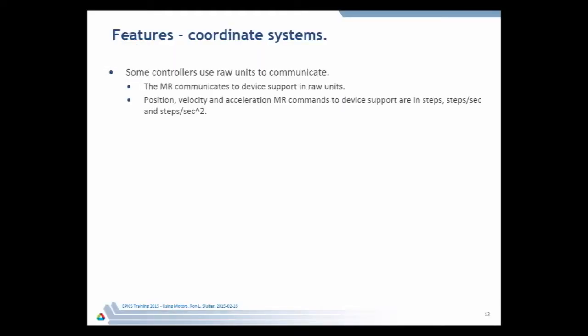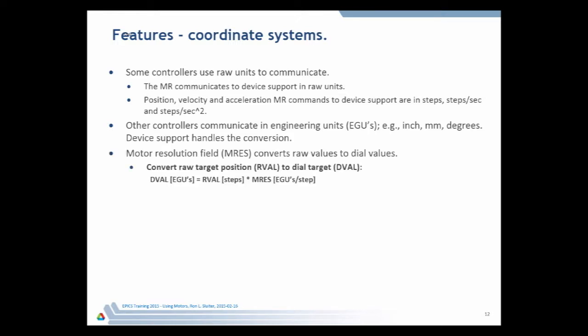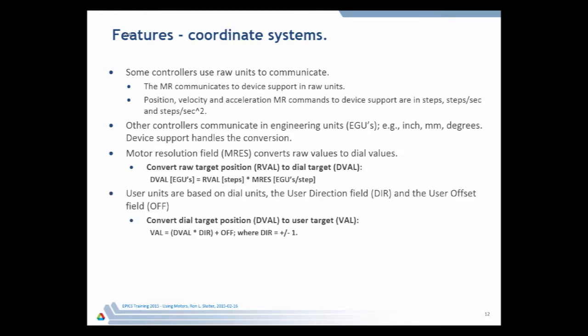Getting back to the device support interface, some controllers use raw units to communicate with, which would be low-level steps or encoder ticks. This tends to be more of the older controllers. And then some controllers use engineering units: inches, millimeters, degrees. It's the device support layer's responsibility to handle that conversion between units. These are simply some algebraic expressions of what's shown in that previous diagram.